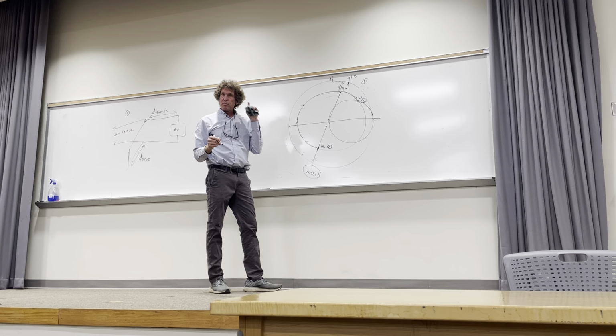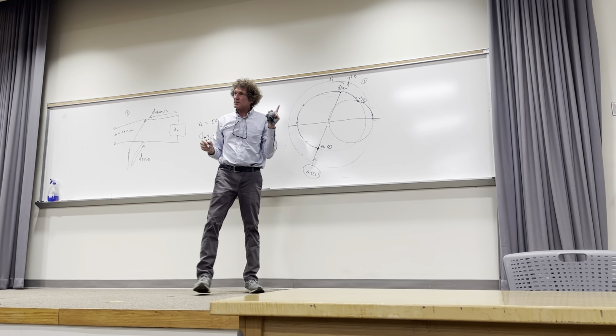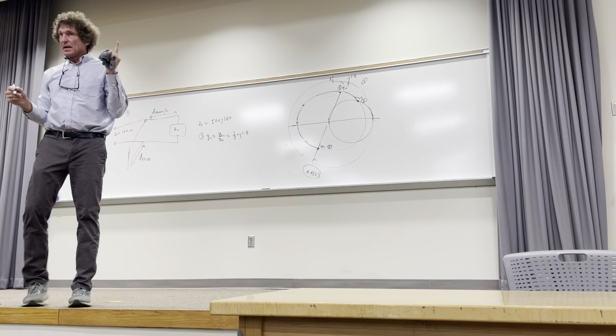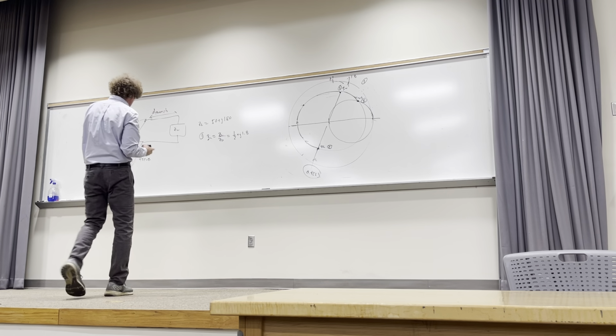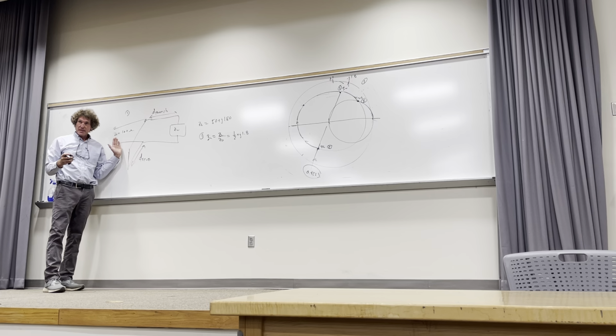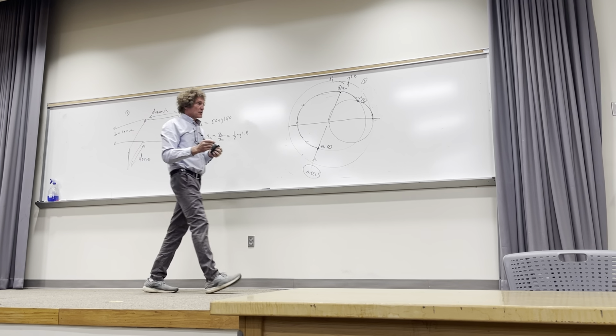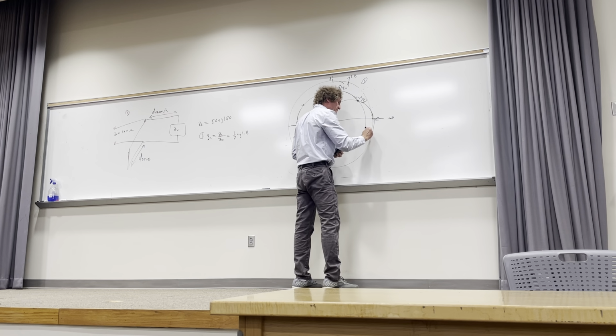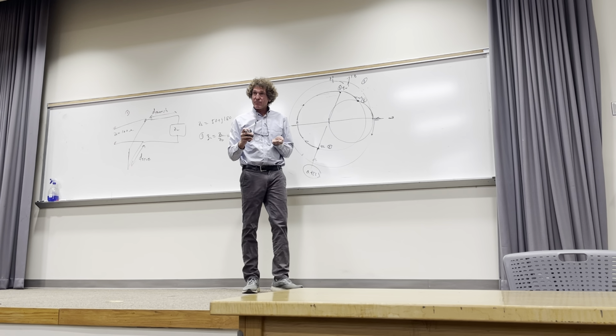We're gonna have 1 plus J something. The reason it's 1 plus J something is because I asked the stub to be minimized, right? Now you know ahead of time, if this is a short circuit stub, its impedance is 0, but its admittance is infinite, even when normalized, right? So when you come in for the stub, you're going to be coming into this point, which is infinity, and when you go this way, this is all negative. Do y'all follow me on this class?